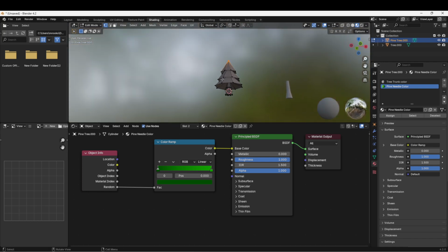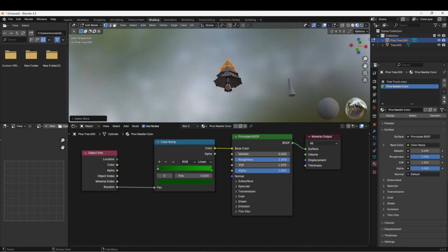We're going to use a new shortcut, and it's the add selection. So we're going to press Control and the plus sign once, and it will select everything connected to our top. Control plus sign again will go up inside and select the underneath. So if we keep pressing that, we can see that we slowly select everything until we get to the tree trunk. If you accidentally select too much by hitting Control plus sign, you can hit Control minus and it will remove something.